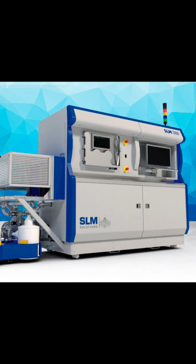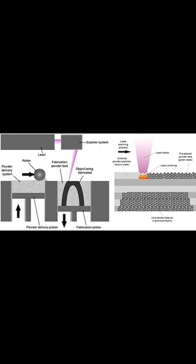SLM, also known as selective laser melting, uses a variety of alloys, allowing prototypes to be functional hardware made out of the same material as production components. Since the components are built by layer, it is possible to design organic geometries, internal features, and challenging passages. SLM produces strong, durable metal parts that work well as both functional prototypes or end-use production parts.